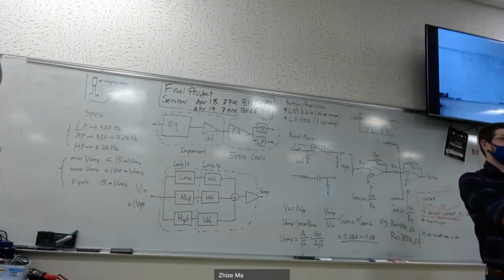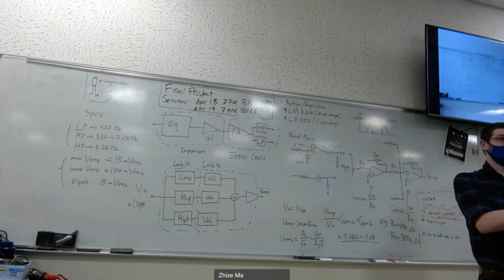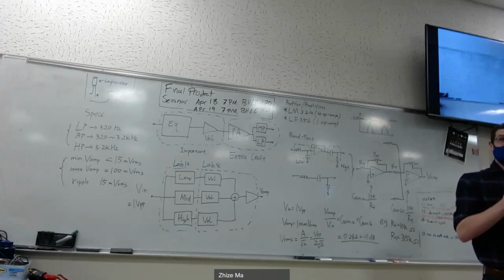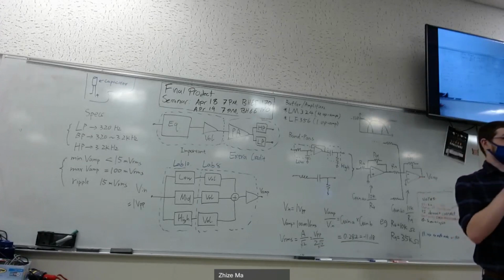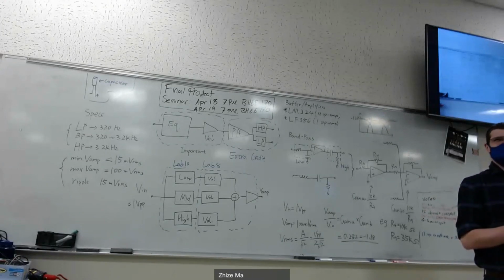As you guys did it yourself, you probably realized that the lower the resistance, the louder noise you get, but it comes with a lot of static. Right, and often if it goes too low, you get that high-pitched squeal again. If you notice that they're way too high, then you get way too quiet of a noise, even though it may sound beautiful. So finding that middle equal ground, there's not really a good calculation for that. So that's a little bit of trial and error on their side. Personally, I believe 4.7K is what I used. That seemed to work out pretty well.